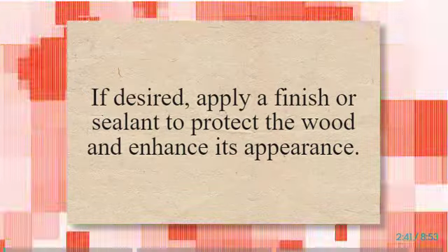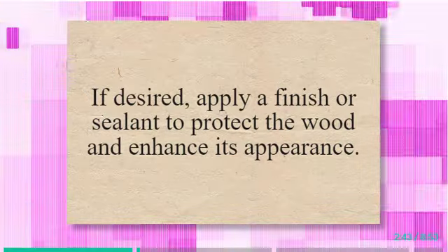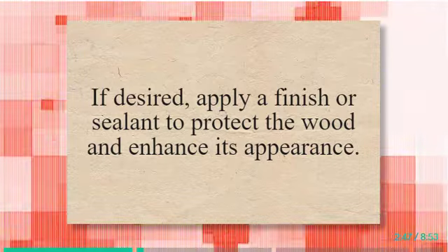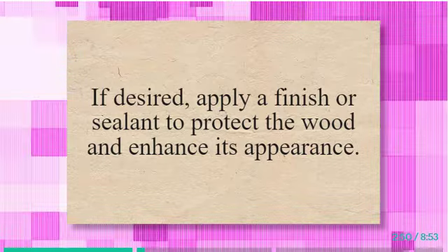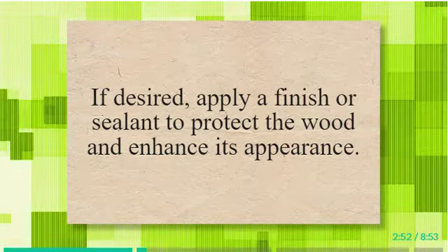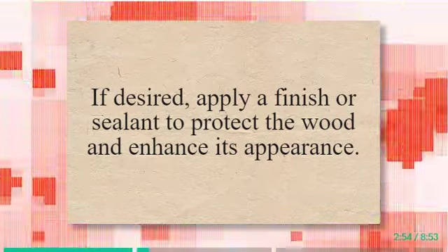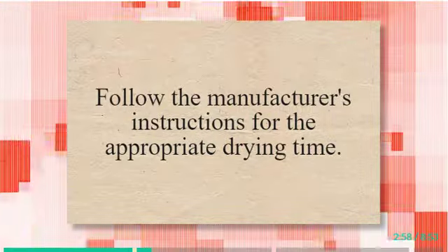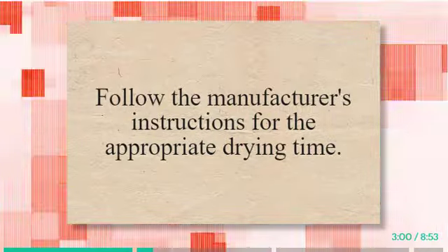Step 8. Finishing touches. Once the entire floor is installed, fill any nail holes with wood putty and sand the whole surface to smooth out any imperfections. If desired, apply a finish or sealant to protect the wood and enhance its appearance. Follow the manufacturer's instructions for the appropriate drying time.